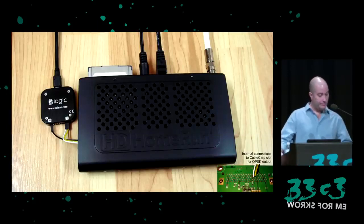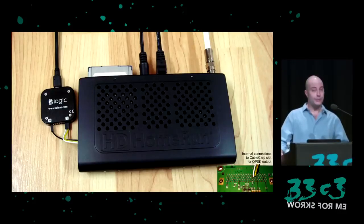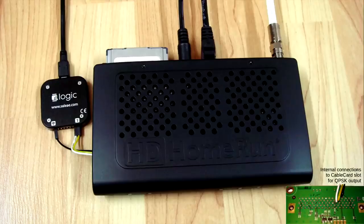Another cable TV adapter is the HD Home Run Prime. This one is a network-connected 3-tuner device with cable card support. The set-top boxes I studied predate the cable cards, although the newer boxes do use the cable cards and they support the DigiCypher 2. But cable card support does also mean that this HD Home Run Prime includes the tuner and QPSK demodulator for the out-of-band channel, so it is able to pass this data to the cable card as necessary. However, even the HD Home Run doesn't make this out-of-band data available other than the cable card interface.